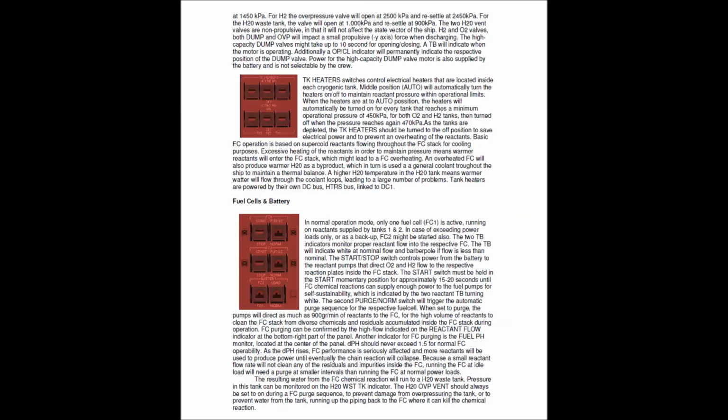As the tanks are depleted, the tank heaters should be turned to the off position to save electrical power and to prevent overheating of the reactants. Basic fuel cell operations is based on super-cold reactants flowing through the FC stack for cooling purposes. Excessive heating of the reactants in order to maintain pressure means warmer reactants will enter the FC stack, which might lead to FC overheating.